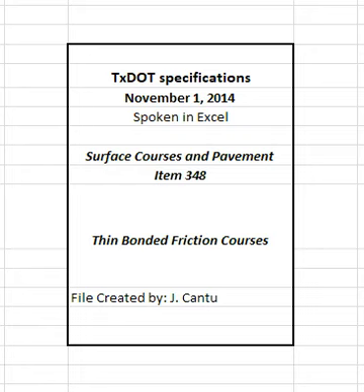2.3 Baghouse fines. Fines collected by the baghouse or other dust collecting equipment may be reintroduced into the mixing drum. 2.4 Asphalt binder. Furnish the type and grade of binder specified on the plans that meets the requirements of Item 300, Asphalts, Oils, and Emulsions. 2.4.1 Performance graded, PG, binder. Provide an asphalt binder with a high temperature grade of PG 76 and low temperature grade as shown on the plans in accordance with Section 300.2.10, Performance Graded Binders, when PG binder is specified.